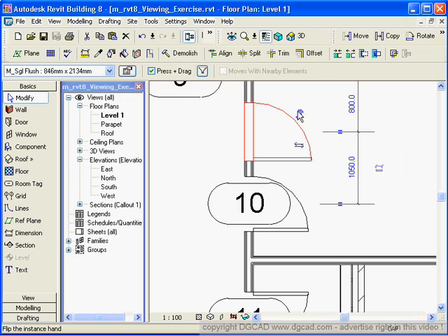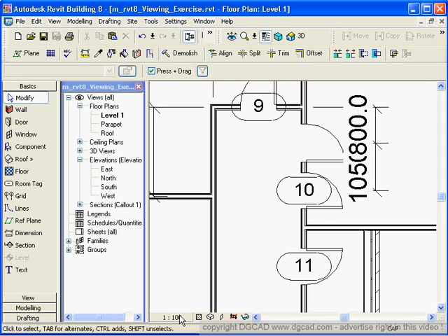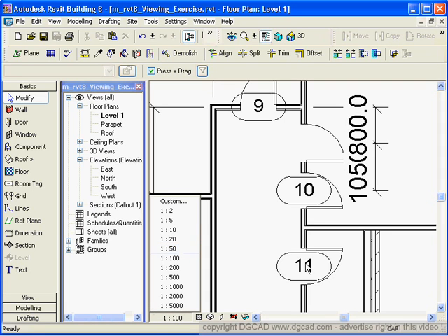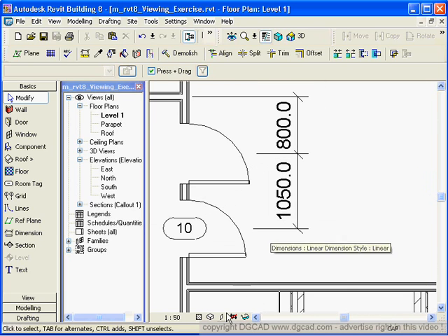After it's in, you can click on it and hit your flip buttons in here and here and flip those around. Again, you can go grab this, make that dimension permanent, and then click and change a number and click out, and it'll put those in. Again, our scale factor here, let's change this back to be 1 to 50, and of course our annotations will all get smaller and all update, which is quite nice.